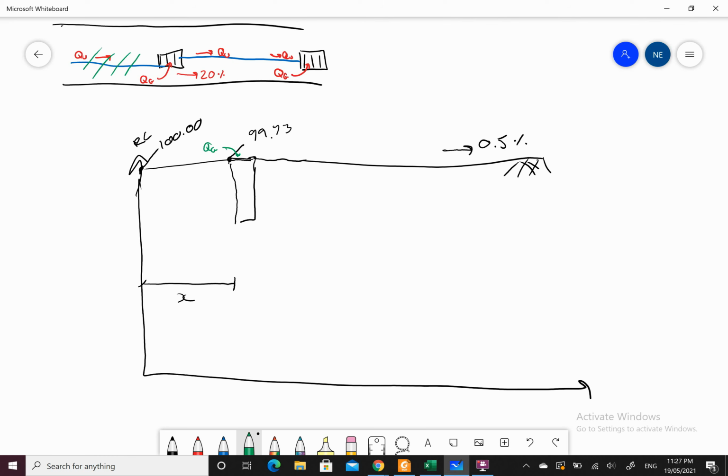We're ignoring any pipe work at the start. We're saying this is the first pit. QG comes in, I have my 300mm freeboard. All right, go through your notes. We say that we don't allow it to be any higher than that. We make sure our water level is stationary or drops at that point. And then it will drop again due to our shock loss. And our hydraulic grade line will continue down.